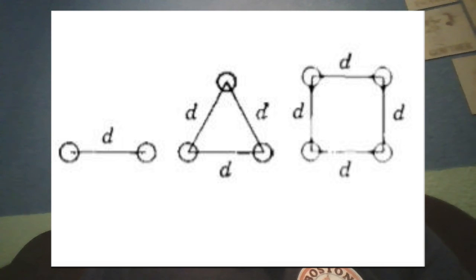The high voltage gradient at the conductor in the EHV range is reduced considerably by having two or more conductors per phase in close proximity compared with the spacing between phases. Such a line is said to be composed of bundled conductors. The bundle consists of two, three, or four conductors.